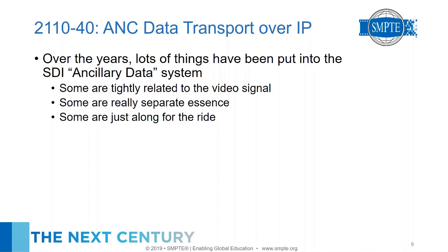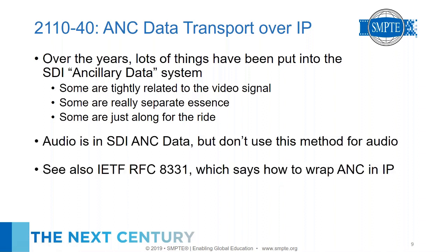Now, 2110-40 is our new standard for ancillary data transport. So all of the things that over the years people have put into the SDI ancillary data system, we wanted to provide a generalized way to accommodate all of those in IP. And so there is a single defined thing, 2110-40, and a related IETF document, RFC 8331, which describe how to wrap ancillary data packets in IP, transport them and timestamp them in a 2110 environment.